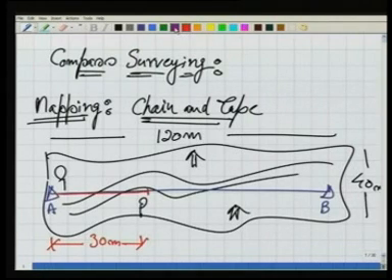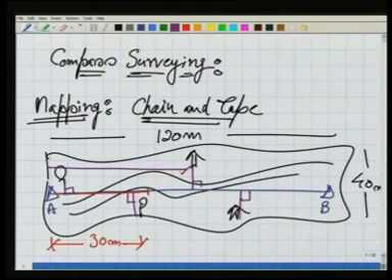So in order to do that, we need to do the ranging. Then later on, for each object, we start taking the offsets. By taking these offsets of the objects from the survey line, we record the chainage. The chainage is the distance along the survey line, and the offset is the distance of the detail. Using this we can do the mapping, we can make the map, we can plot the map.